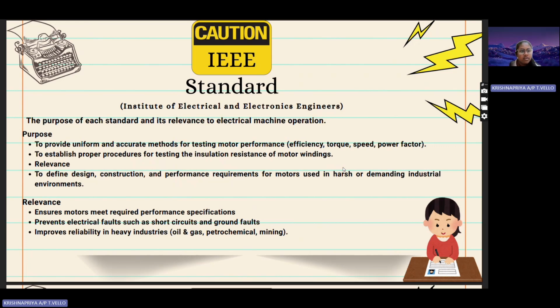For the second one, IEEE 43, the purpose is to establish a proper procedure for testing the insulation resistance of motor windings. It is relevant to prevent electrical faults such as short circuits and ground faults.